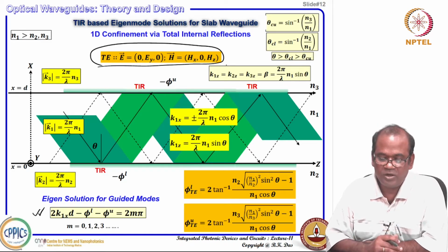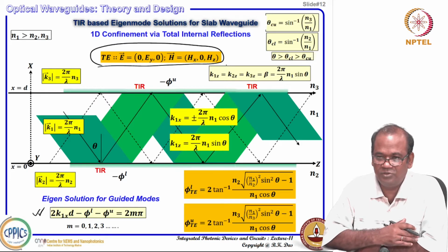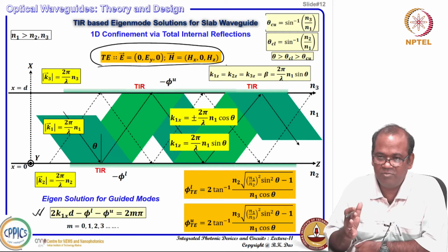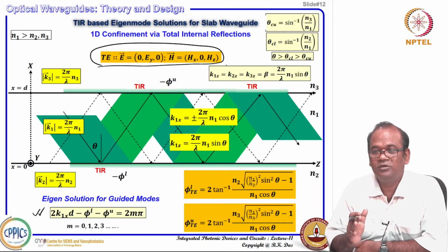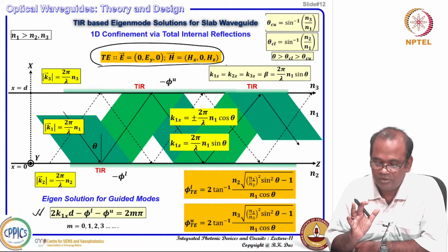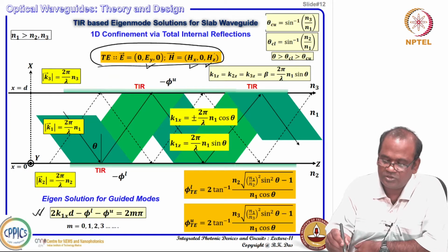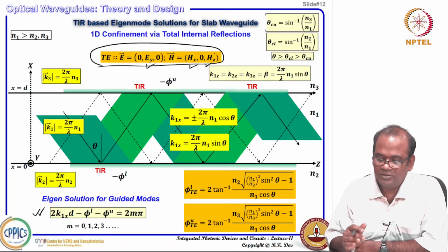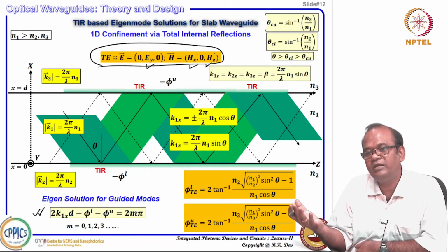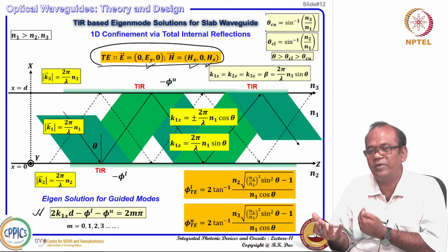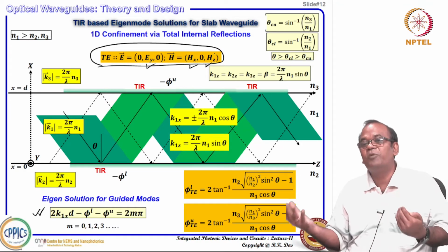That is one type of polarization, we call it TE polarization, and we normally distinguish TE and TM just to take advantage of boundary conditions, without any violation of Maxwell's equations and wave propagation. If I consider these 3 components, that is good enough to carry energy, and another set of 3 components called TM is also good enough to carry energy independently. So, we can treat them separately.